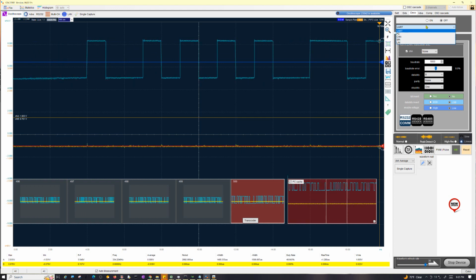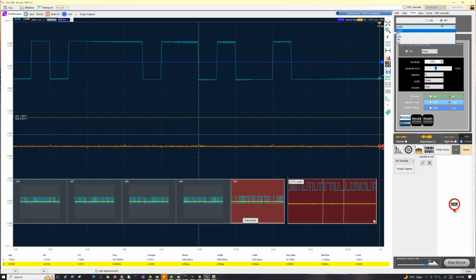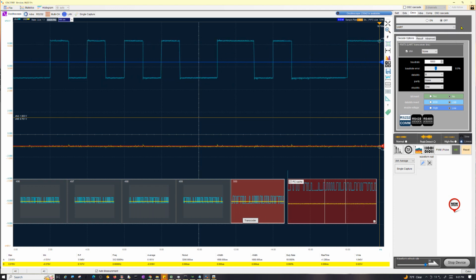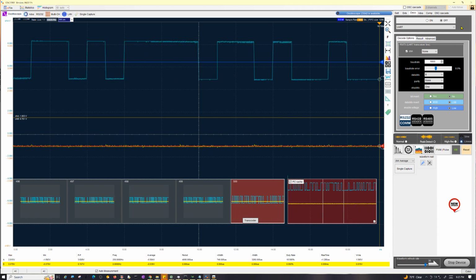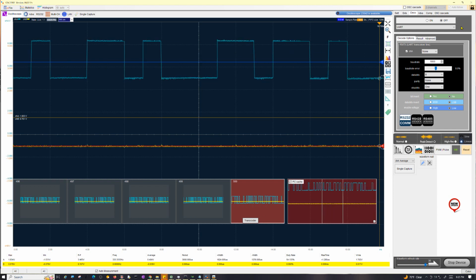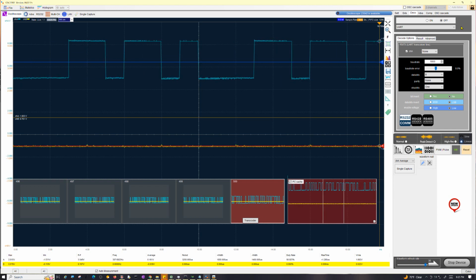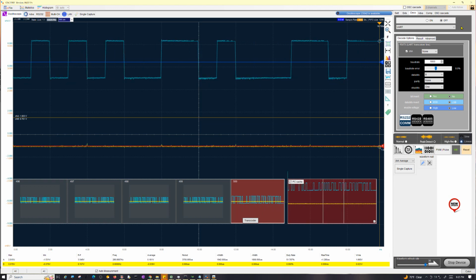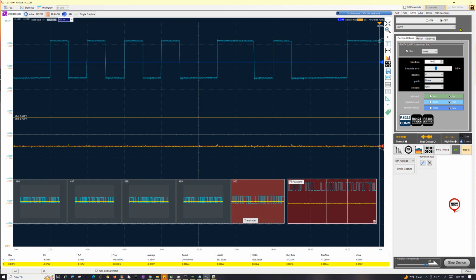But again, this is really only good as a listener if you're looking at decoding. Things I did like about this is that it didn't have too many probes. Like you see the Analog Discovery, it has like 16 channels hanging off. You've got all these wires running everywhere, and it's annoying. In fact, even on this one, I would rather have had the $100 version that only has like 3 or 4 channels, just so I have fewer probes in the way, because you almost don't need any more logic channels than that these days. You're mostly decoding serial buses and so forth.